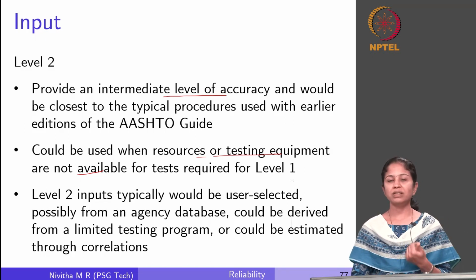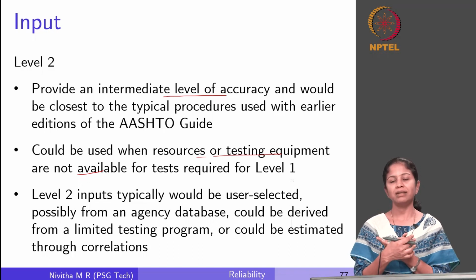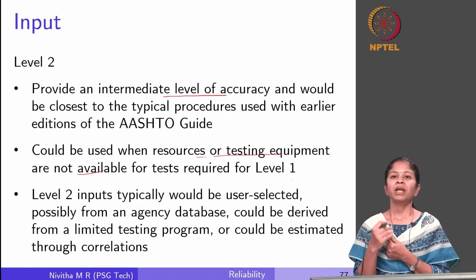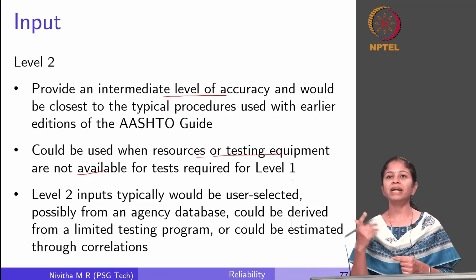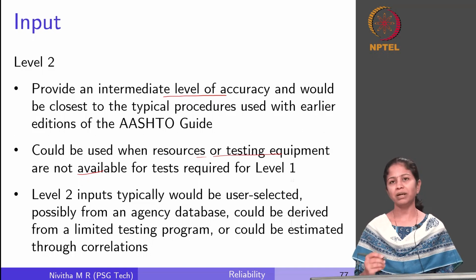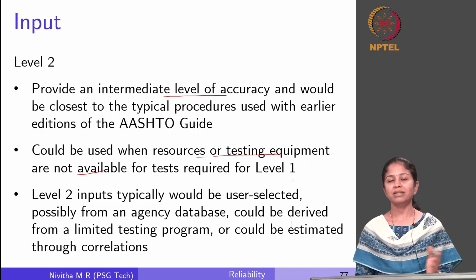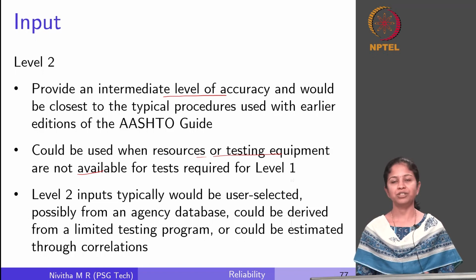Instead what I can do is I can measure the property of binder, I can measure the property of aggregates, right, and then based on these properties of the individual materials, I will use empirical relations to predict the property of bituminous mixture, right. So, I am not directly measuring this value, but I am predicting it using other empirical equations. They may be valid, but there are certain approximations which are used here, obviously, right.